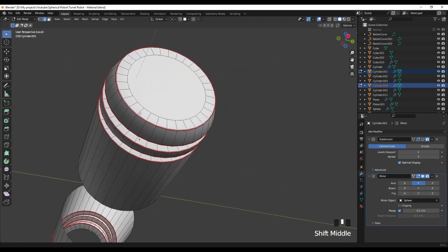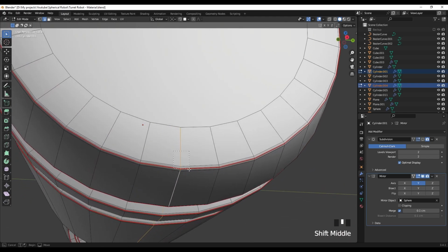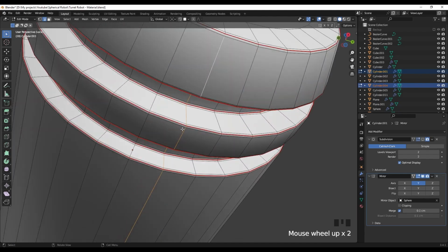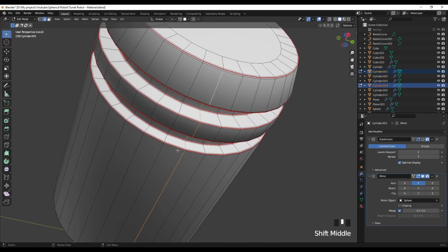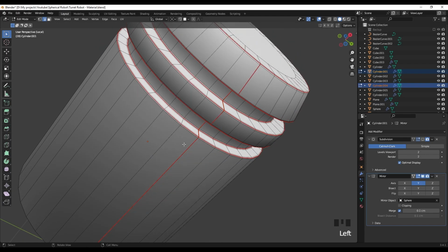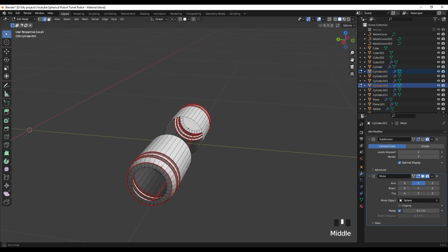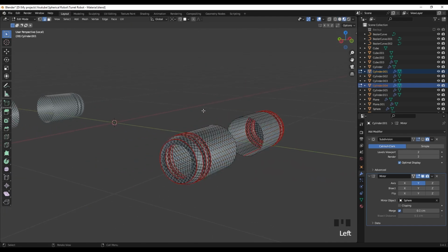So for this one, let's hold Alt and click to make a loop selection and deselect this flat one. Also, we can deselect these flat faces, but I'm gonna leave this and mark edges and select all, U, and unwrap and material preview.